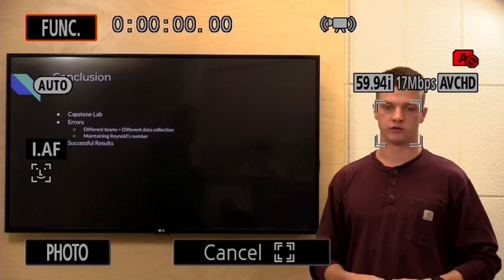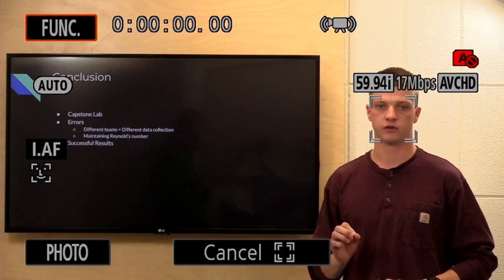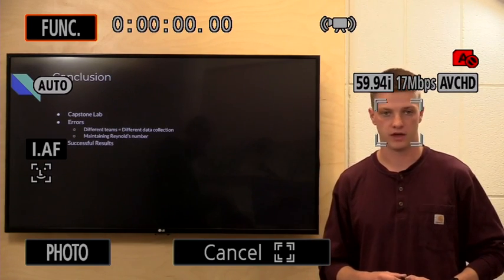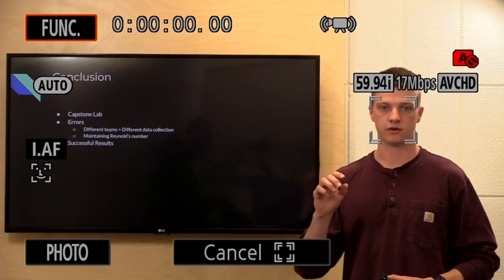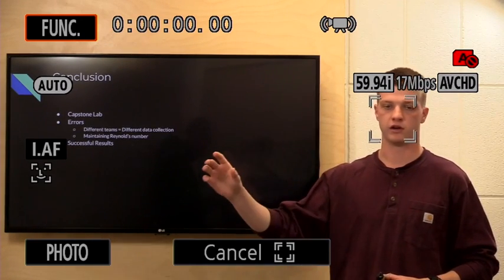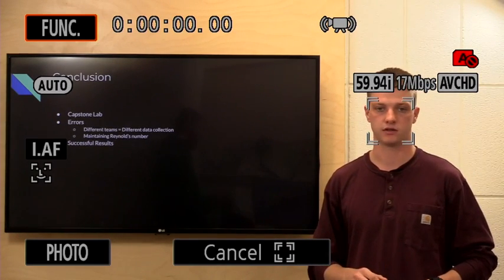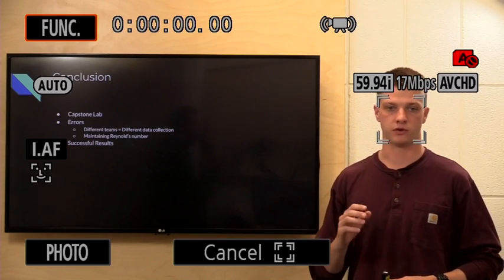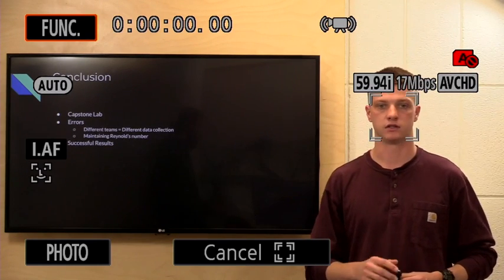Also, maintaining the Reynolds number during our test. So for all of our tests, our ideal Reynolds number was about 700,000, and in order to maintain that number, we had to maintain a constant speed in the wind tunnel. And in order to maintain a constant speed, someone had to control the dial, which would then in turn read off the pressure transducer, which would give us a voltage that we wanted to remain constant. And it was a very hard job for that person to do. And so although it was human error, it's also almost impossible to maintain a completely constant speed in the wind tunnel.